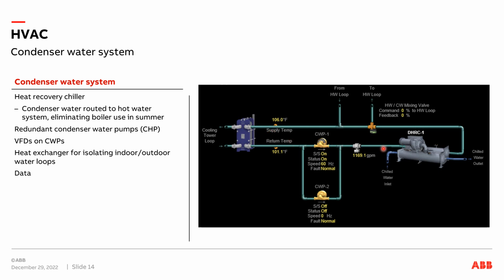So what we do is take our condenser water, which is getting hot basically for free, because we're spending all our money and energy to get the chilled water created, and this is more of a side effect that's a nuisance for us. Let's take that nuisance hot water that just happens because of physics and take advantage of it. They also call it condenser water. The condenser water goes to what we call the hot water loop, which is specific to our heating system, and we leverage that condenser water to heat our VAV reheats during the summer.